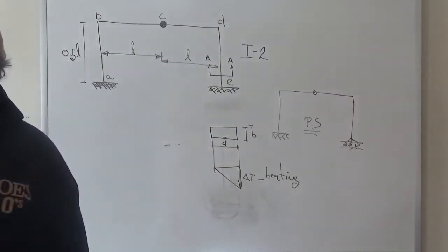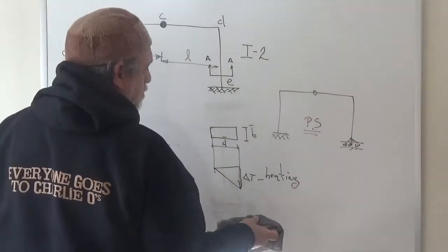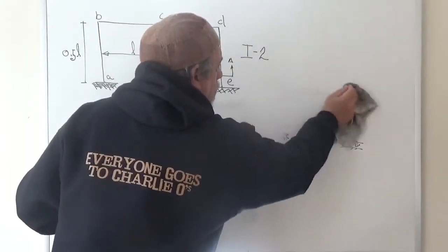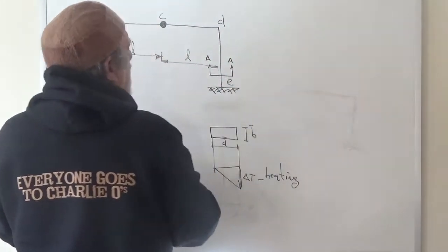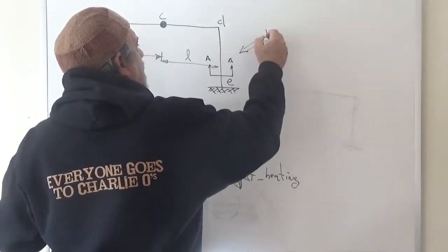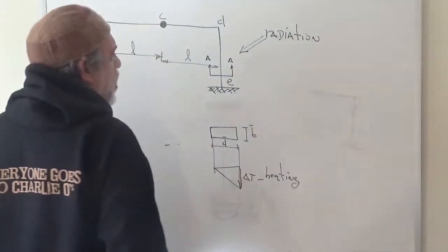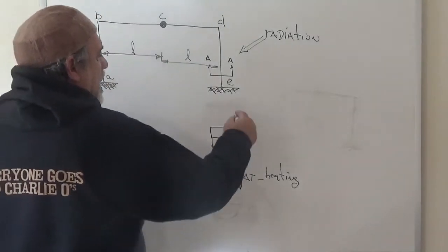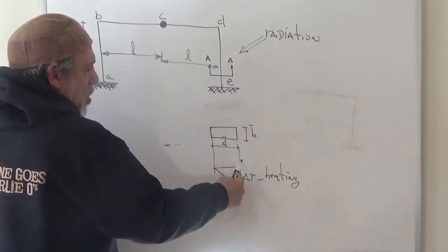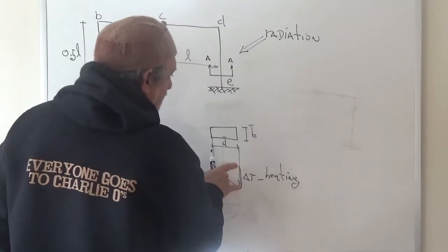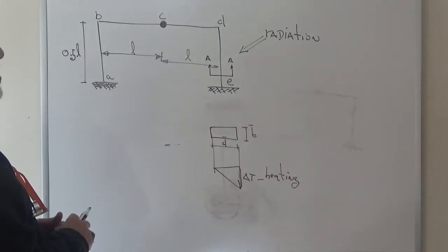This is saying something like if the sun, right, if there was radiation from the sun hitting the outside of the column there, then that side of the column which is receiving the sun radiation is heating up, and we are looking at a moment in time when the outside fibers have heated up by delta T while the inside fibers have not changed temperature.